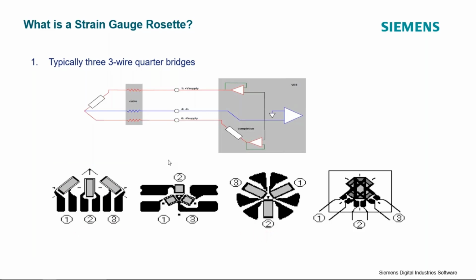And what these strain gauge rosettes allow us to do is basically by measuring the strains and doing some math, we can determine the maximum principal strains that the device under test is experiencing at that point. We can determine the maximum shear strains, and we can also then use that information to calculate basically a strain history versus time of any kind of angular orientation of our gauge.